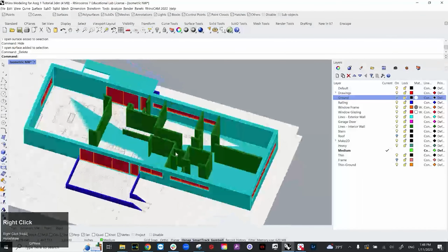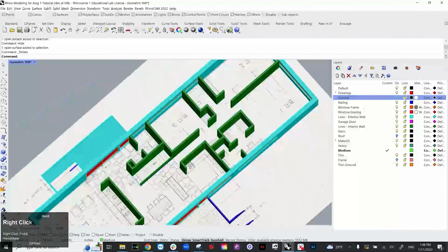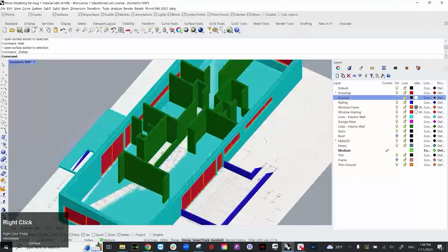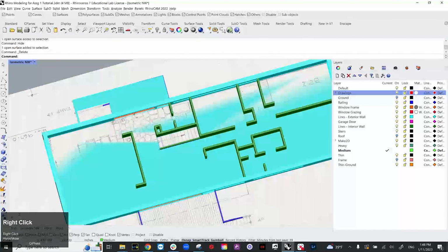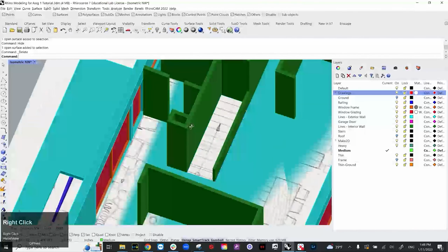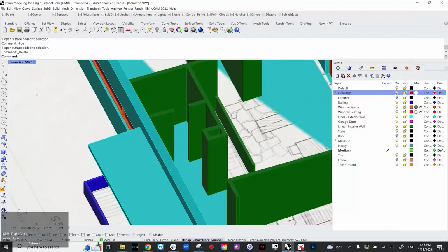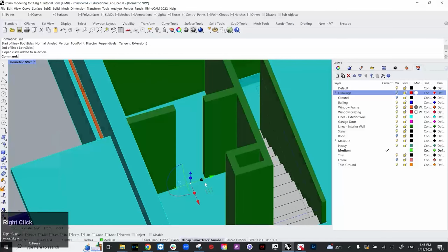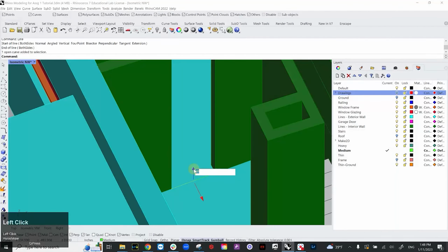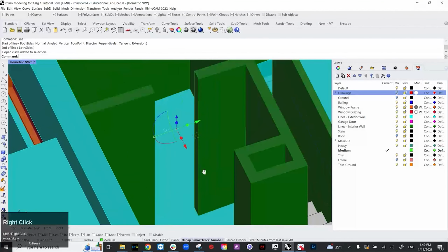So first things we are going to do is create a door for the interior space. So looking at the floor plans over here, there is a door here. So I'm gonna start from there. The regular height of the door is about 80 inches. They come in a couple different sizes, of course. But we are going to assume that door is 80 inches at the moment. So that's 6 feet and 8 inches. So create that line over here, move that up by 80. So that's the top of the doors.